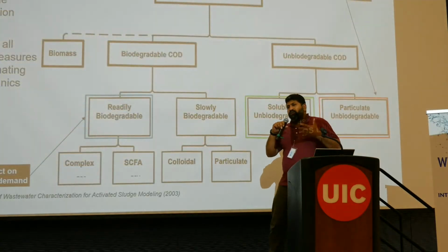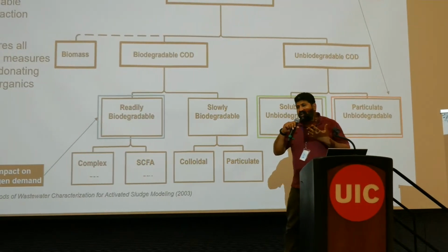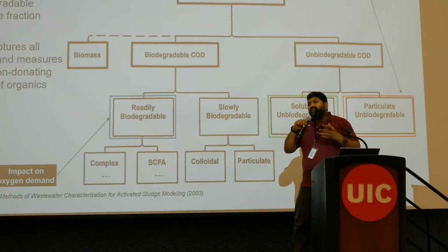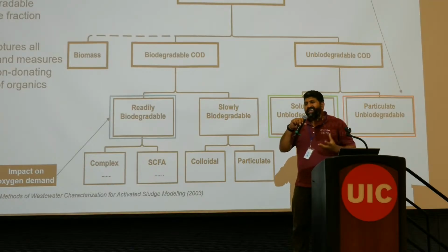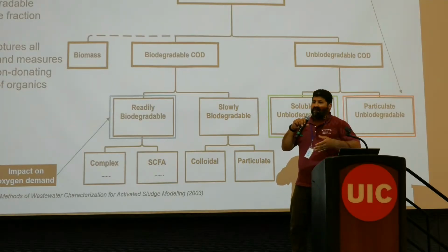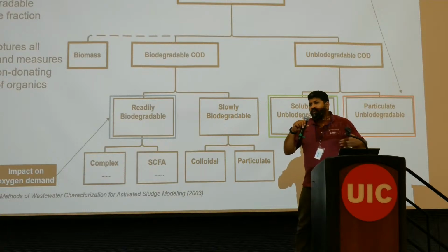So how do you go about unpacking this problem? You need to look from a mass balance standpoint at what is in your wastewater. Because a lot of times the carbon, which is the COD, is one of the key elements you are trying to understand, and how much of that is readily biodegradable. And in tropical climates where the ambient temperature is higher, the activity is also higher, so the basin sizes are quite small.